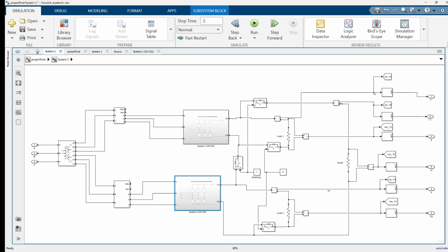We are also considering 80% voltage derating of the diodes and SCRs, which is applied to each device to ensure safe operation under transient conditions. Therefore we are choosing the diodes and the SCRs of 600 volt. Peak is 600 volt, right? PIV.